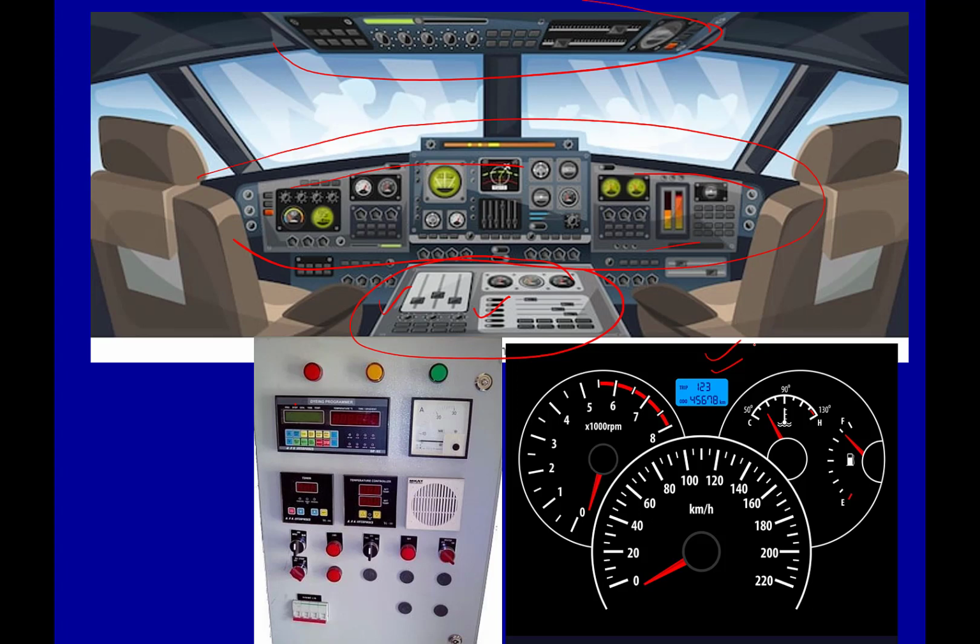In all these cases, you will see that the scale is fixed and the pointer is moving. So you have a very wide range and you also get the accuracy of the data. This is the most versatile one, because it covers a wide range and shows the data accurately. When the rate of change of data is not that high, then these kinds of displays are used very effectively.